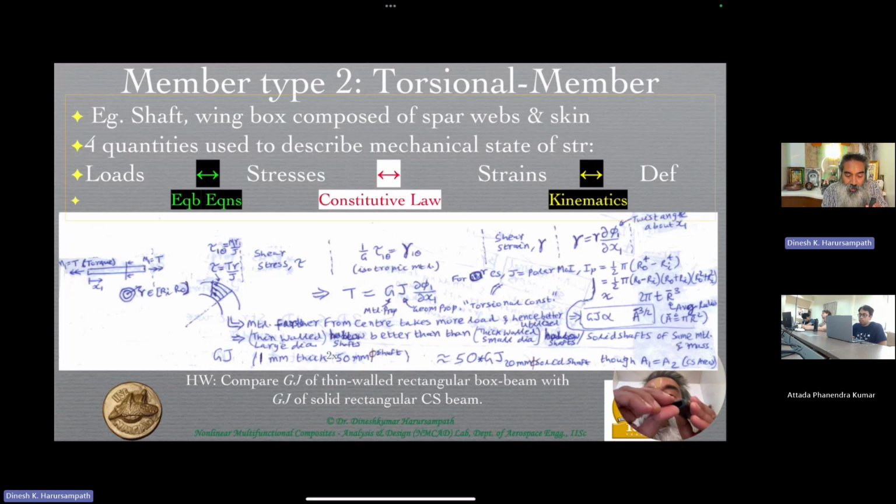But since it is outboard, the moment arm for the force acting through that stress integrated over the area is going to be much more now, because the material has been put outward, and therefore the radius is much larger, which is the same as the moment arm, and therefore a larger radius means a larger moment arm, therefore a larger capability to resist the torque.